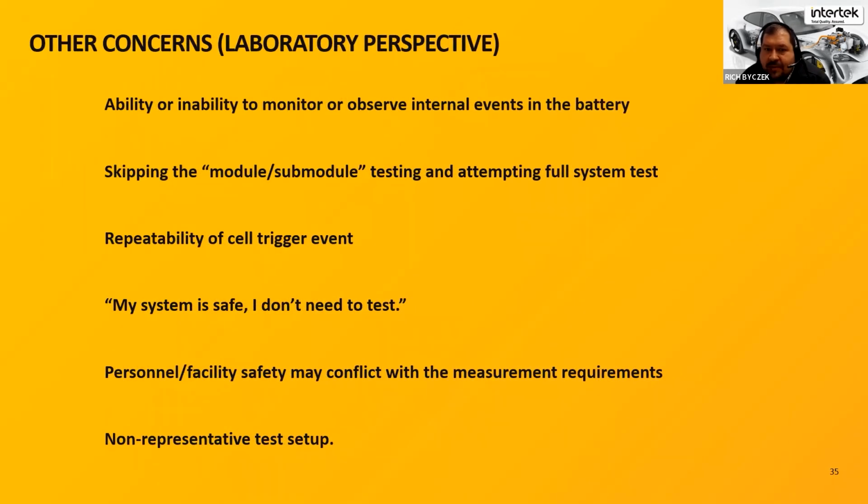Concerns from a laboratory standpoint, it's very difficult to observe the internals of a large battery system. At the single cell, it's very easy to monitor temperatures, look at it with a thermal camera, look at it with an optical camera. Once you put that inside a module with all the enclosures, et cetera, you're limited to a few data points that can tell you exactly how the cell propagates from one to the other.